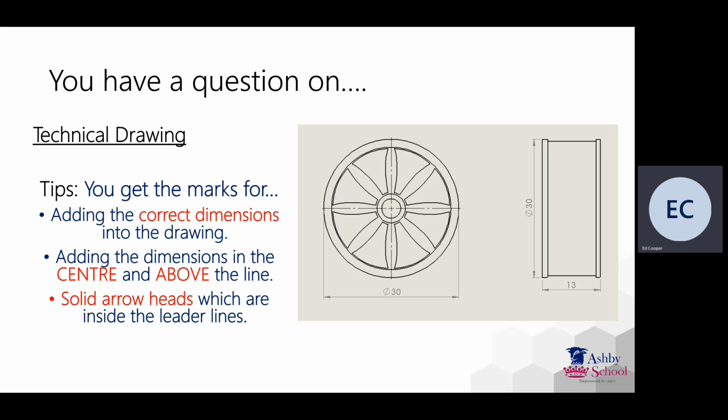Okay, the final one to notice as well, you've got arrowheads that are long and thin, coloured in. Okay, it should be about 3 times the length going left to right here where my pointer is, as it is high. Okay, so it's long and thin, and they're solid black, coloured in. So remember the little rhyme, long and thin, coloured in.